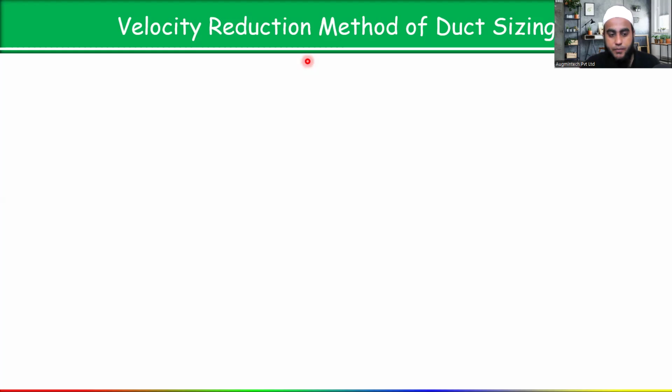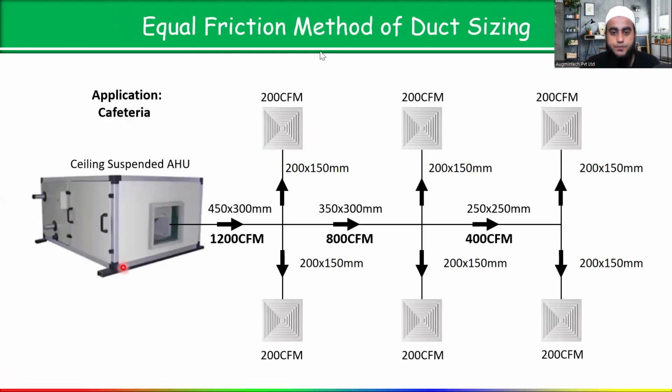Regarding the branch duct size, someone is asking whether we need to size the branch duct based on the diffuser neck size. Yes. In a diffuser, generally we have a face size, which you see from the top view in the AutoCAD file. In the catalog, or in any software you use for diffuser selection and sizing, the size written is the neck size of the diffuser. Face size varies from manufacturer to manufacturer. As per GGC, Gulf Grill Corporation, the face size should be 1.5 to 2 times greater than the neck size. I will show you an example so you get the idea.